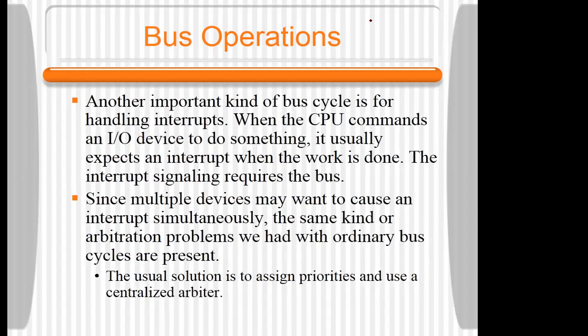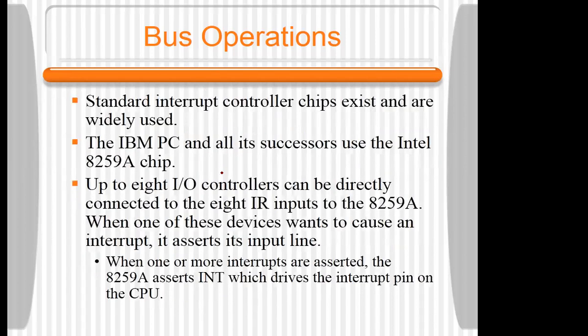We're saying that signal which a device gives to show that it is requesting to use the bus, or to show that it is using the bus, or to show that it has used up its own time or is finished using the bus. Those are now handled as interrupts by our interrupt handling devices, which are also chips which are used for that. So those controller chips are widely used, and in IBM systems, they normally use the Intel chips for interrupt handling.